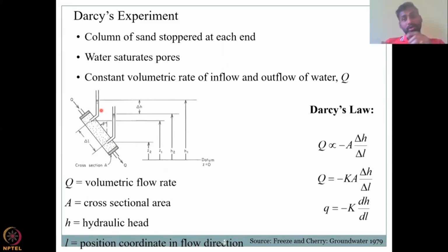So to understand the flow, he put 2 monitoring points, and between the points, he's going to calculate the well hydraulics and the hydrology, groundwater hydrology movement. The first well is called well A, and then the well B is in a lower elevation. And why does water move from top to bottom? Because water flows from high potential to low potential.